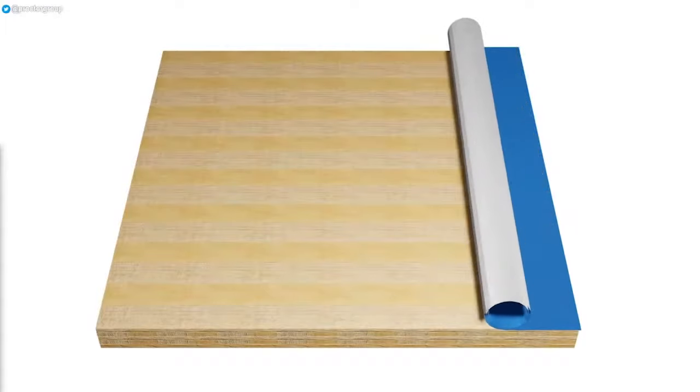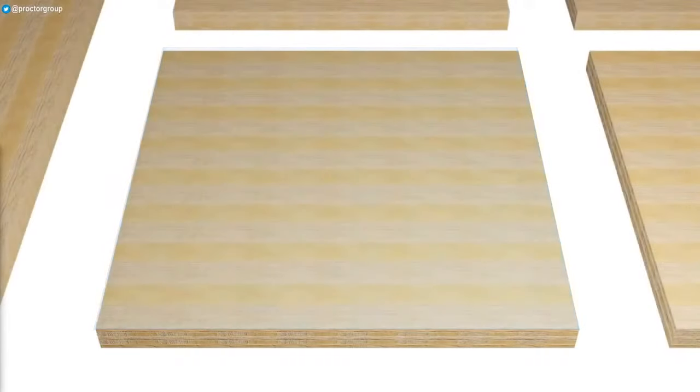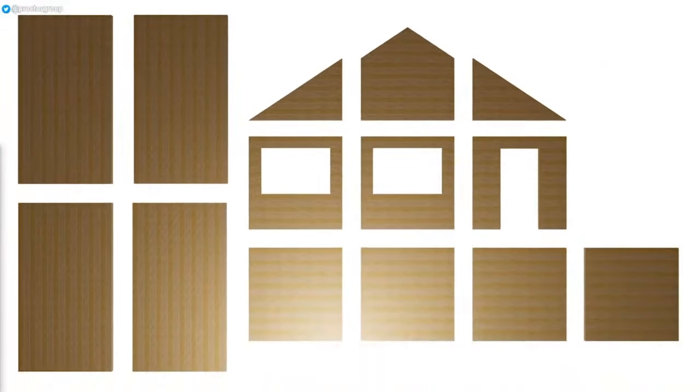The panels can then be fitted with a vapour permeable membrane to protect them during transit to site and limit the amount of pre-completion moisture within the panels. They can also be left uncovered, with membranes added after the layers of insulation later in the construction process. These panels can in theory be any size and shape, but in practice, manufacturing and transportation considerations tend to limit the size to around 3 metres by 16 metres.